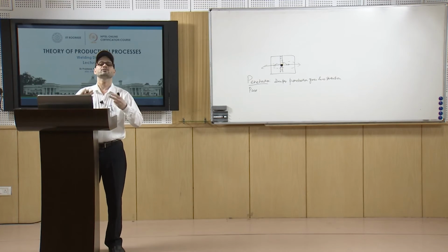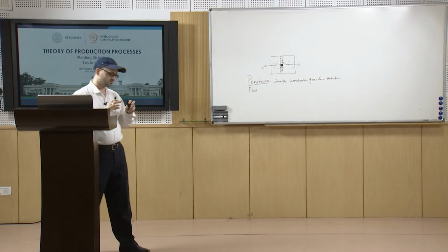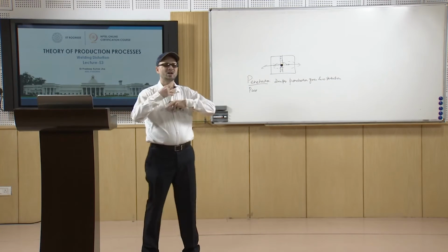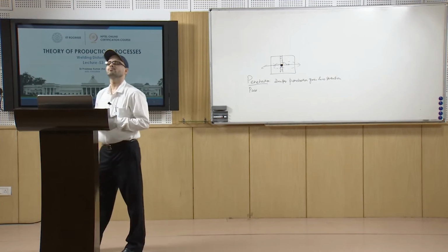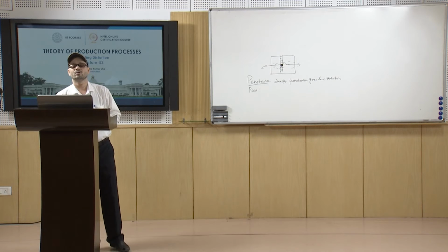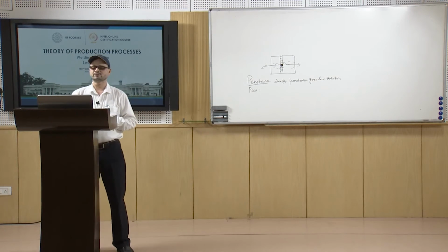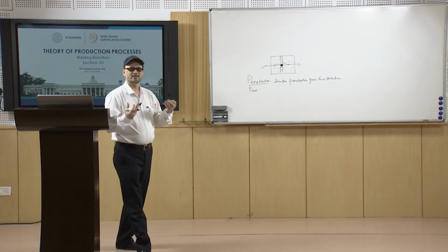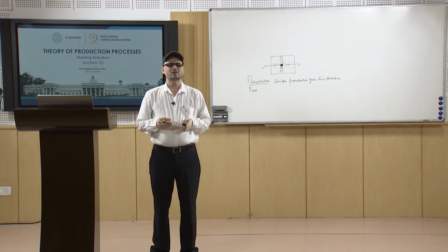Then you have the length of the weld and also the moment of inertia of the structure. Based on these parameters we normally calculate the longitudinal distortion of the welded structure, and we calculate these values in terms of numeric values. This way longitudinal distortion is calculated.